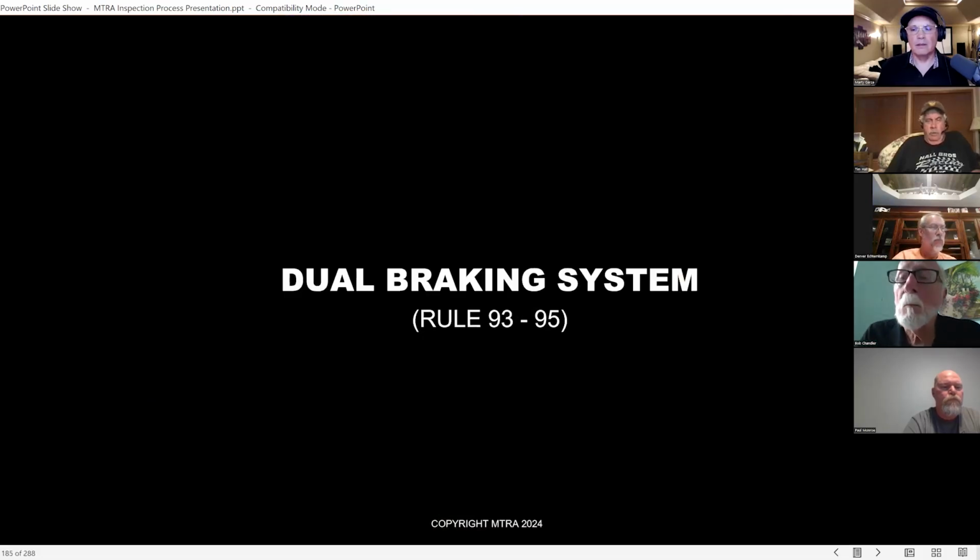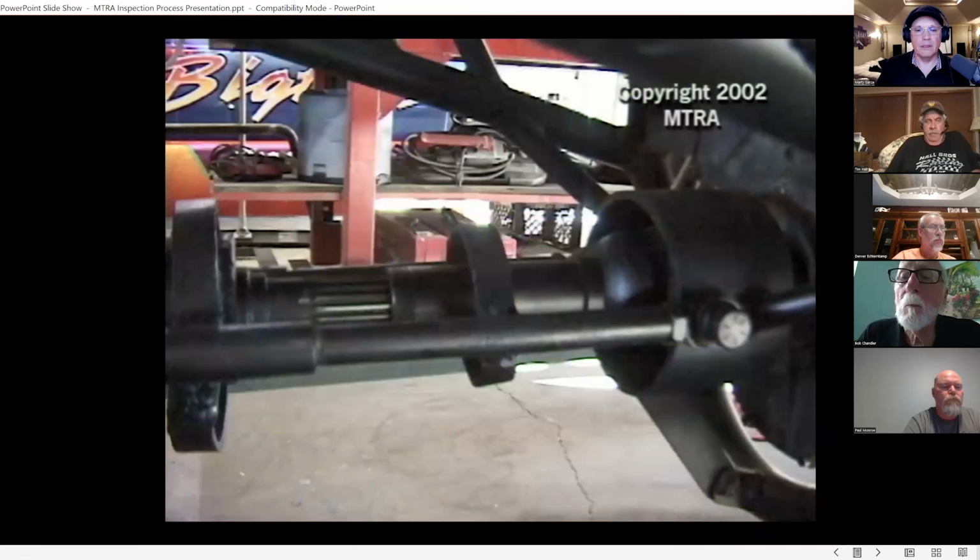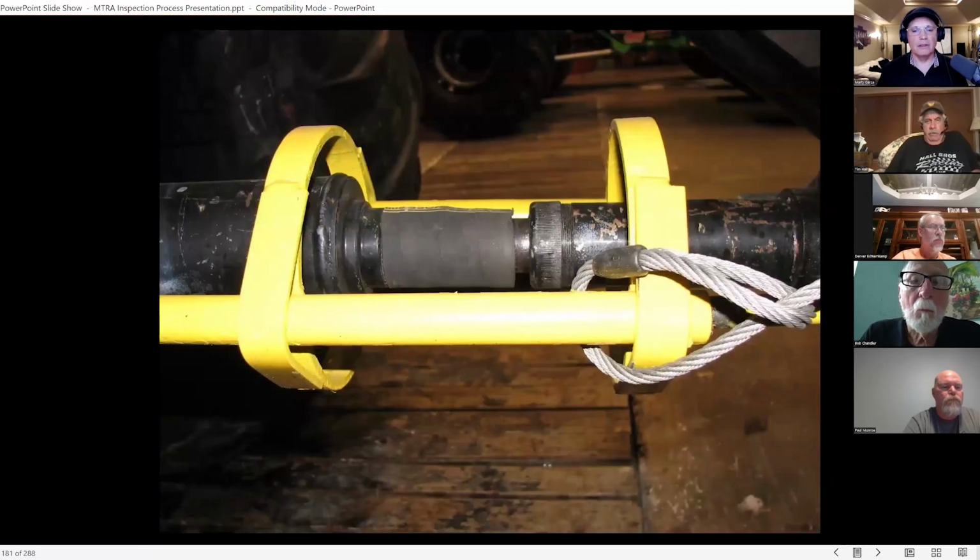And you also showed a picture there with a rubber sleeve. Yeah, that's a thing now that Feld requires, and I think some other promoters are starting to require. They want that rubber sleeve on there. It's a piece of hose, and the idea is that if the U-joint failed and the slip yoke was loose, it can't slide together too far and get out of the containment shield. It still allows the drive shaft to move: it just smashes the rubber and then returns back, so it doesn't hurt anything.